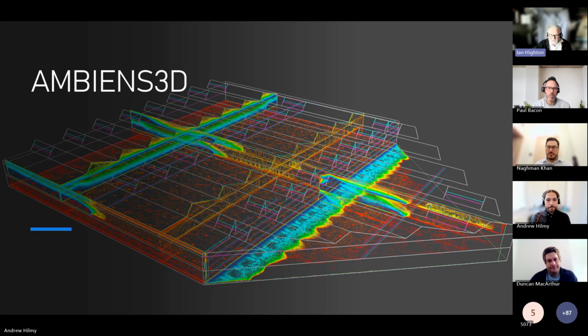Most current CFD software packages use a thing called pressure correction to try and conserve mass. Basically, the continuity equation has just got U, V, W in it, so it's all just velocities, whereas the momentum equations also have the pressure terms in there. So what you do is effectively turn that continuity equation into a pressure equation by saying, if I change the pressure, can I then conserve the mass?